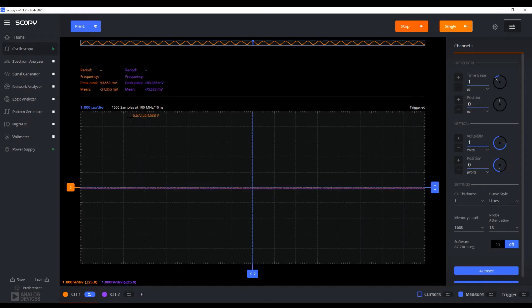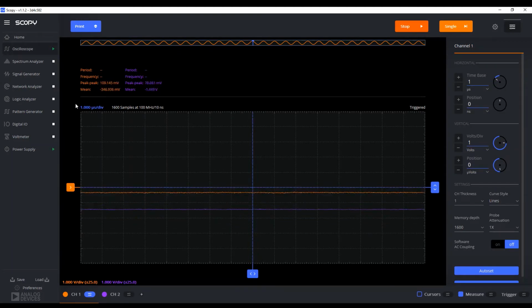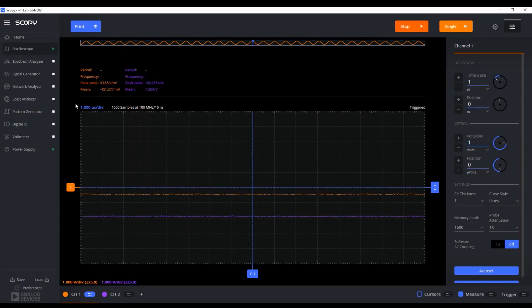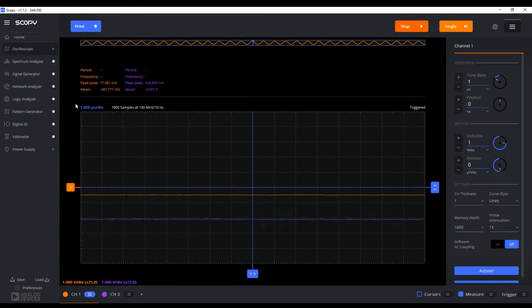So now we're going to shine a light through it to see how the voltage across channel 2 increases. As you can see, shining it closely now, channel 1 is increasing, channel 2 is also increasing, but at a higher rate. And if we use the same input voltage as I used in the report, which is about negative 400 millivolts, let's see. Yeah, that's about negative 400 millivolts. There we go. As you can see, it's close to 1.9, which is the value I calculated using the gain equation. More about that in the report.